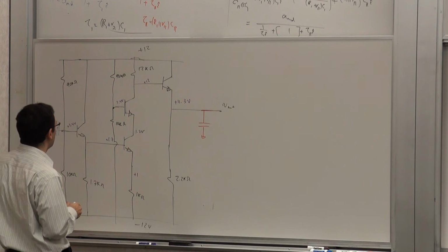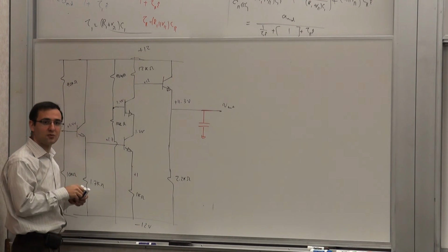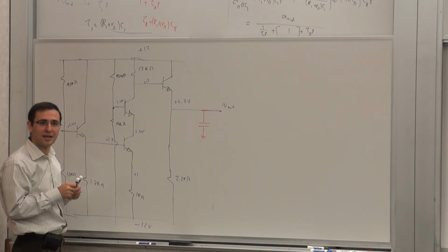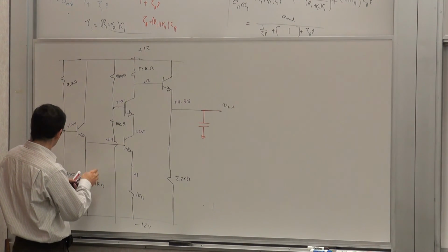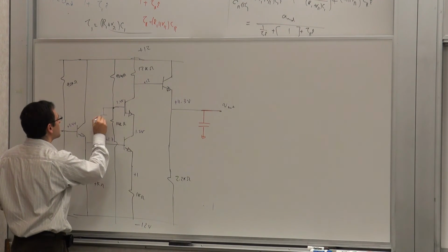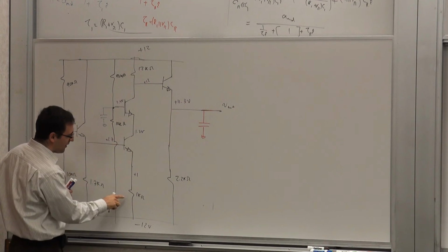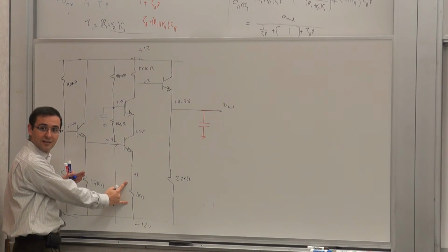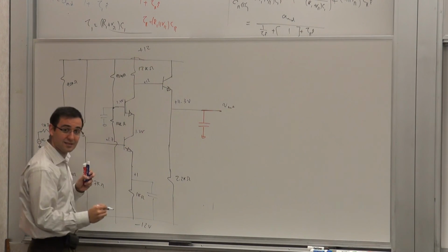And then I need to do something about here too. Because at the base, I assume it's low frequency, it's a short, right? But this is not short, it's a high impedance, so I have to put a capacitor here. So I have to decouple this one. And now, if I do it this way, I get very little gain, right? Because I haven't bypassed this guy. This was for biasing, remember? So I just want to bypass it so I get the maximum gain. So this is the bypass.